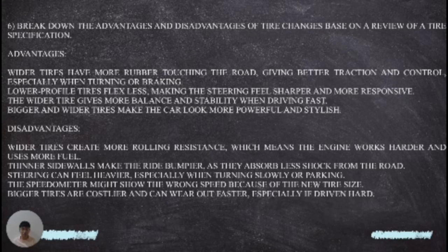However, there are also disadvantages. Wider tires create more rolling resistance, which means the engine must work harder and use more fuel. Thinner sidewalls make the ride bumpier and absorb less shock from the road. The steering can feel heavier, and the speedometer reading might be inaccurate due to the new size. Finally, bigger tires are more expensive and can wear out faster, especially with aggressive driving.